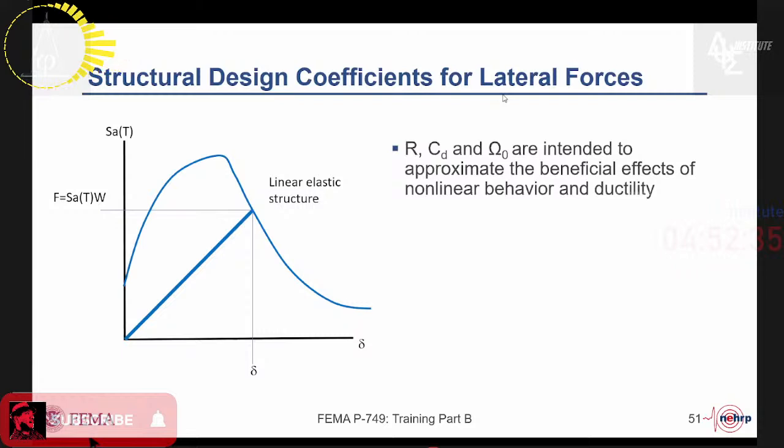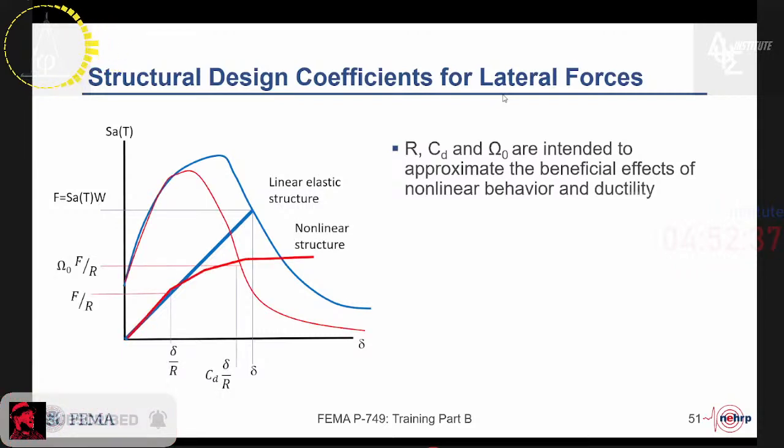As I said earlier, we typically design our structures to exhibit nonlinear response. The nonlinear response of the structure that I've drawn here in the form of a pushover curve accounts for the fact that as a structure takes on damage, it softens and becomes less stiff and also experiences less force. And the effect of that nonlinearity is also to modify the spectrum that the structure is experiencing through the damping that inherently occurs as a result of that nonlinear response.